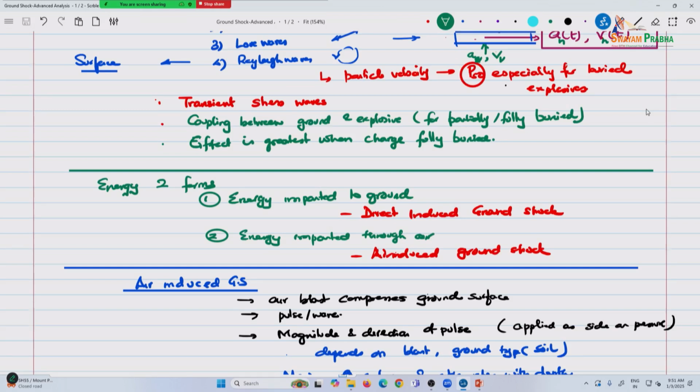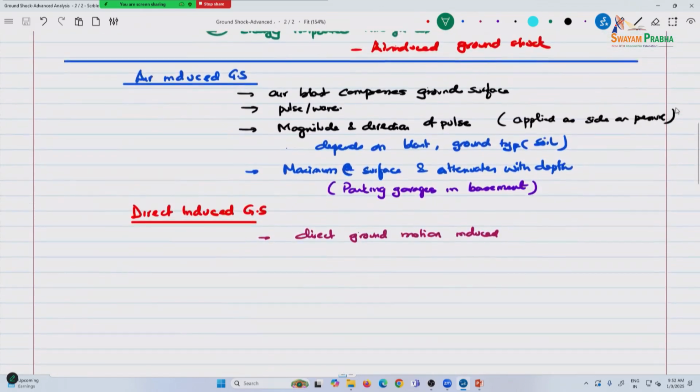So if you're going to shake something, there's going to be free vibration, so to speak, or damped vibration of the structure due to the motion. Now, vertical accelerations, they cause motion up and down. Only recently in the codes we have started incorporating, there have been advocates for that, and now you can see in ASCE 7-22 and maybe even the slightly earlier version, ground accelerations on certain types of structures. They don't affect all types of structures, but those types of structures have started coming into the code. And here we haven't done research to that extent, but that's something you can look at.